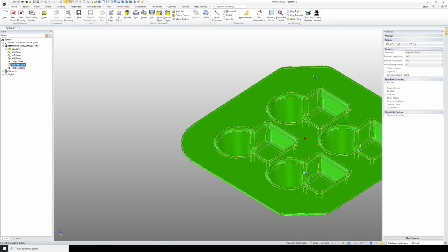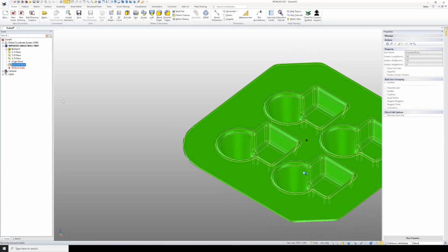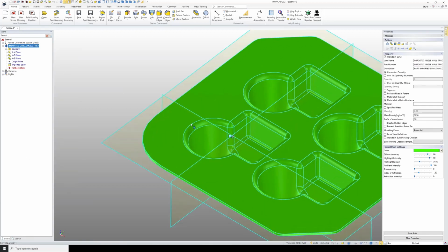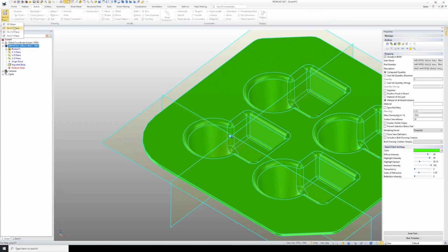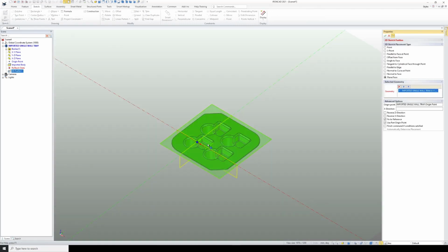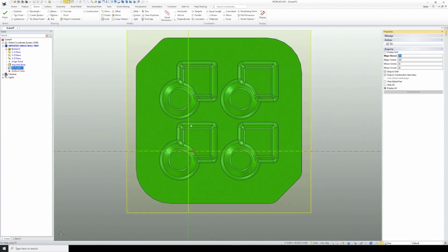So now I don't care about all the rest of the geometry, I'm only interested in this area here. So now I'm going to make sure this is set to active, and I'm going to create a sketch. Go to our 2D sketch tools, and we'll select our plane, which I want to be this plane here, and I'm okay with the origin. Okay. And now what I want to do is project the geometry from this existing tray.